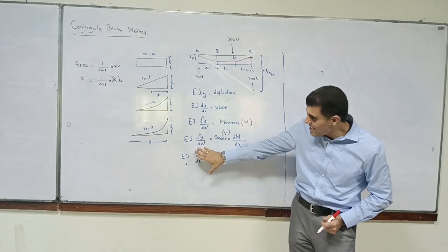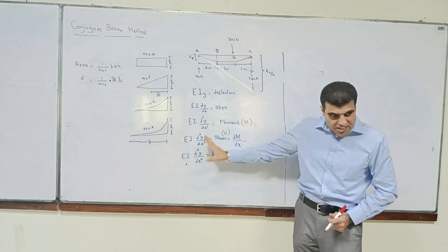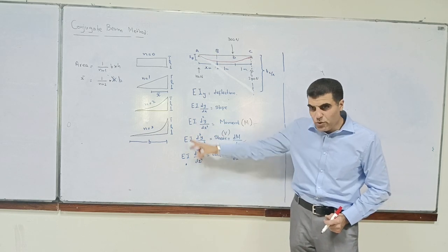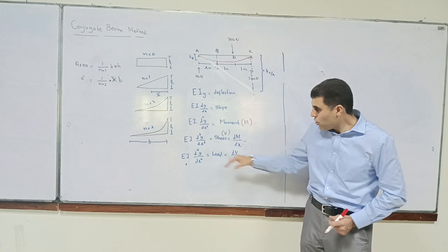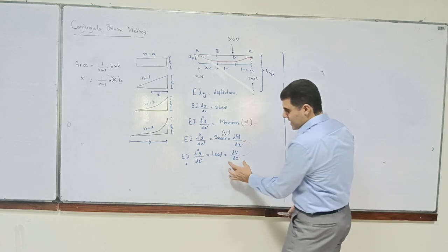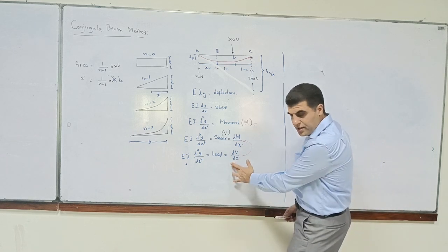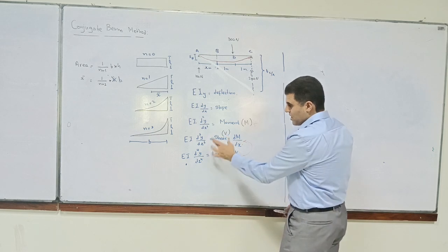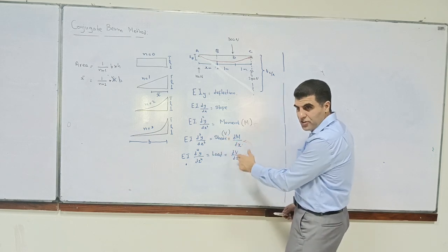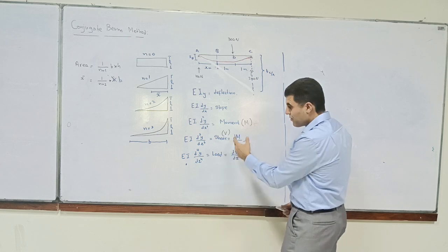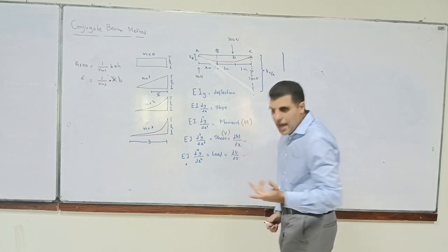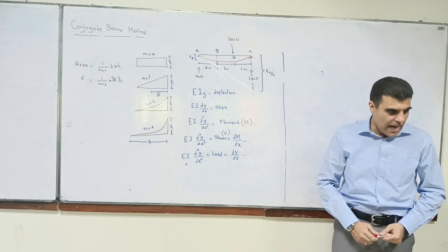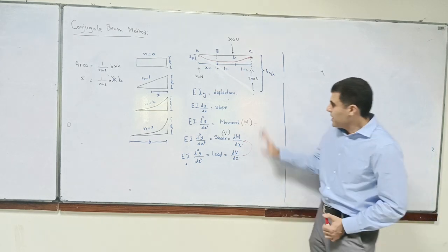They are connected via your differential equations. The load is connected to the first differential of shear, and the shear is connected to the first differential of moment. That's how these three items are connected.